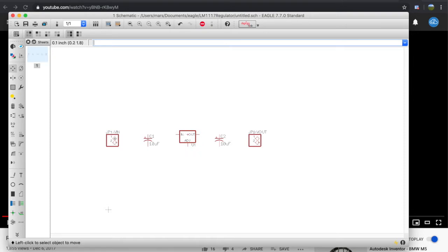Okay, and now to make connections, we're actually going to need something called the wire tool. And it's somewhere around here. There it is. Yeah, that's the one. Okay, and you just click on the component terminals or leads, and you click once, and it'll start wiring. And when you click once again, you can still keep wiring. To finish, you actually have to double click. So like right here, where my wiring connection ends, I double click, and as you can see, it turns from light green to dark green.